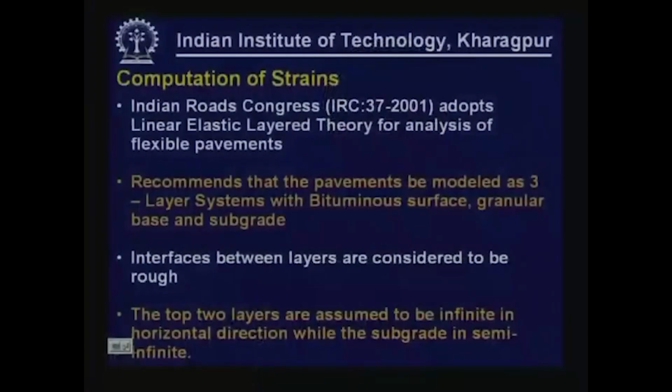The interfaces between the layers, that is, between the bituminous surface and granular base, and the subgrade, are considered to be rough interfaces. We can analyze these pavements with smooth interfaces or with rough interfaces also, but IRC considers the analysis to have rough interfaces.